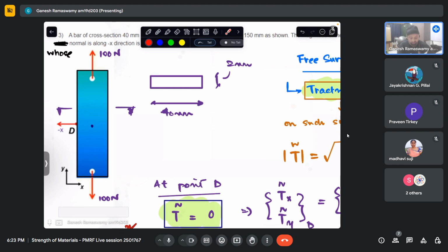We are taking the body and trying to solve for the stresses at each and every point in it. For that, we need to specify the boundary condition and the governing equations that characterize the stress inside. So having no shear when I take a normal like that is the outcome of the analysis.